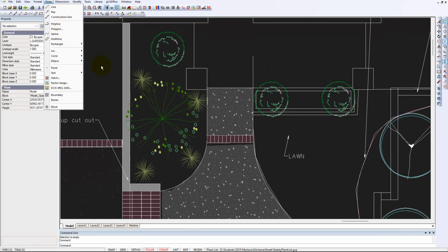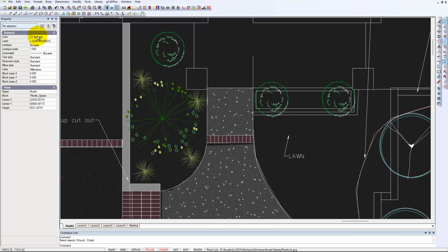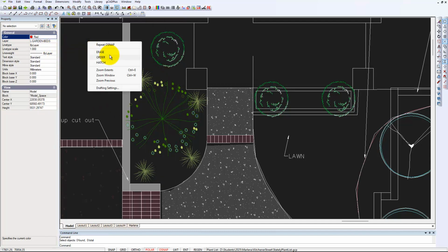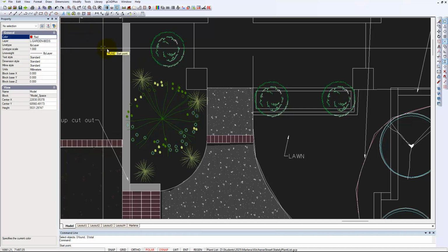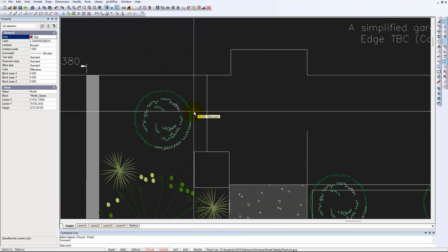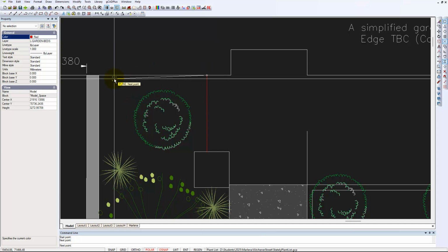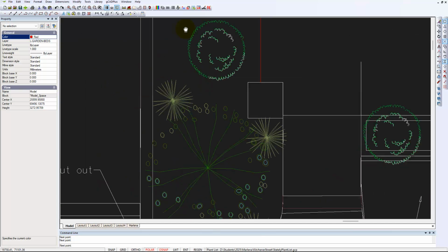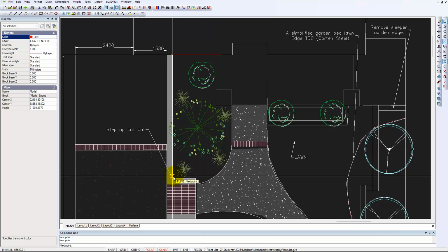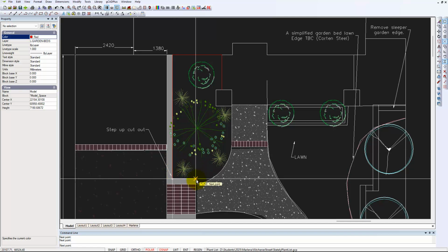Actually, what I'll do first is change my drawing color so that you can see it a little easier. And I'll make the color red, so we should get a red line now. Draw polyline, and let's zoom in a bit. We should be able to find, let's say, that intersection, that endpoint there, and come down, another intersection, another there and there.